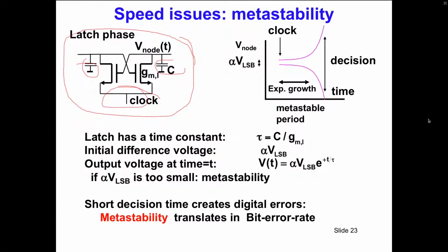And if you activate that, then the voltage difference on the node, here for instance, is a starting voltage, a fraction of an LSB. At the moment the clock hits, then basically you get a linear response, because you basically get at that point a positive exponential function that is still in the linear description until you hit over here the power supply or the ground line.